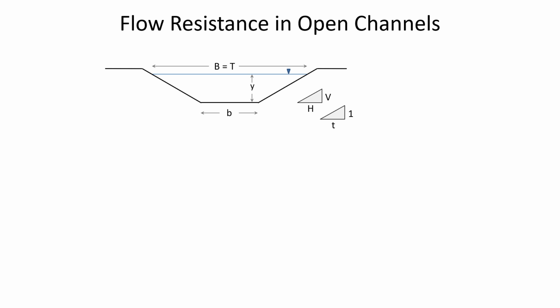All right, we have an open channel here, a rectangular open channel. No, trapezoidal. I really am discombobulated today. This is a trapezoidal channel, and you're going to get really good at dealing with the geometry of a trapezoidal channel, because most engineered channels that are carrying water use the trapezoidal shape, especially if you've got soil or grass lining on the edges.